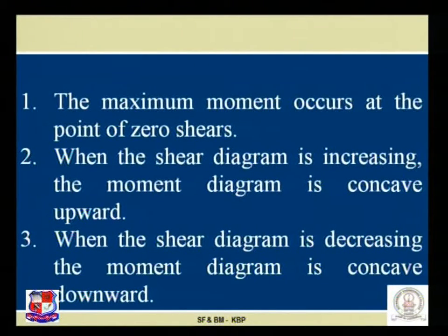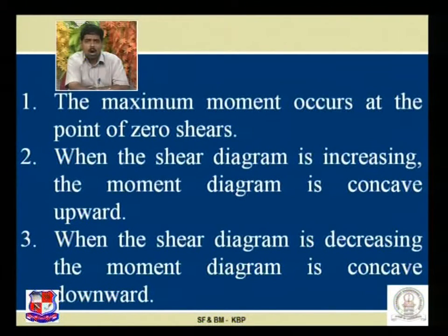Next observation, the maximum moment occurs at the point of zero shear, which we have derived from the equation. When the shear diagram is increasing, the moment diagram is concave upward. Very interesting observation. Next, when the shear diagram is decreasing, the bending moment diagram is concave downward.